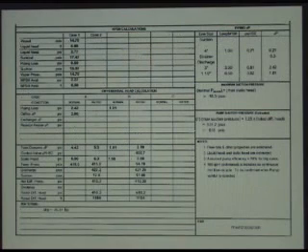But there's also a strainer. So here's the piping loss calculations. Okay, so that means that at the suction of the pump, you've got the total pressure within the vessel and the head of the vessel minus the piping losses, so you get 16.97 psia. Then you subtract the vapor pressure of the fluid, which is 14.7 because it's an atmospheric vessel, and you end up with the NPSHA of 2.27 psi or 6.56 feet of head.